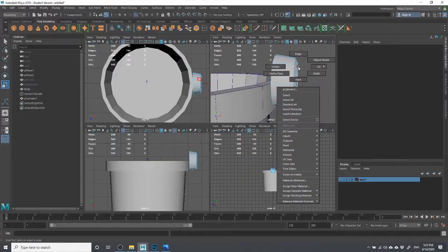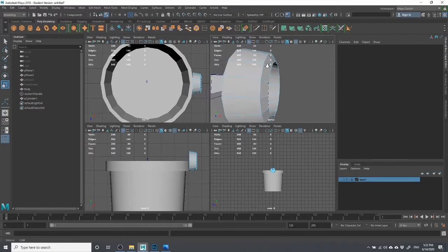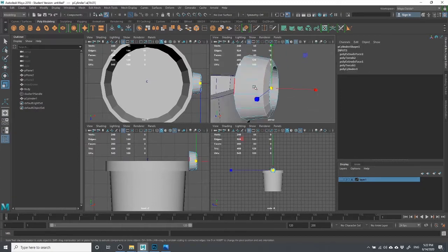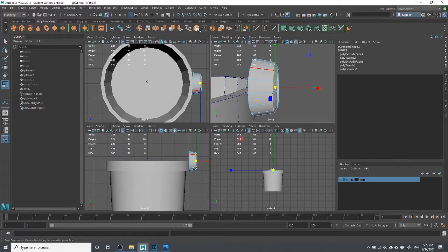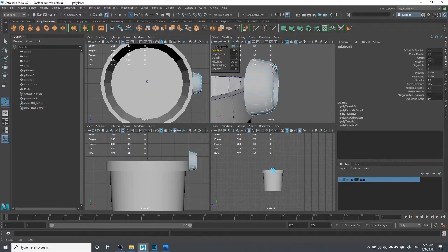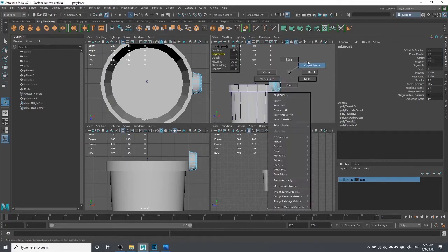One thing I might want to do to round out the edges of this is take that center edge, and by using a bevel, you can make this corner a little softer. The fraction gives you the size of the slope. The segments are cool because the more segments you have, the rounder it's going to get, based on the separate edges here. So I've got this in place, which is cool, and that is pretty much the hinge that I'm looking for.